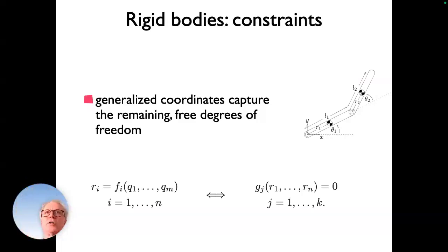Yes, so there are two aspects here. One is the one that you might be getting at, which we call interaction torques. I'll refer to that a little later. For instance, if I actuate this joint and accelerate around this joint, there is some torque felt because of the non-inertial frame in this joint. If I don't do anything, then my wrist will be flopping around due to what we call interaction torques. That is, torques brought onto the elbow will exert a torque on the wrist as well, because it puts the wrist into a non-inertial frame. So these apparent forces arise.